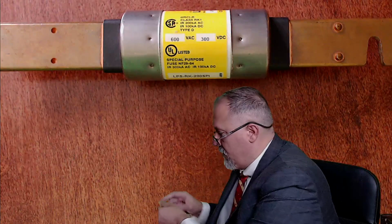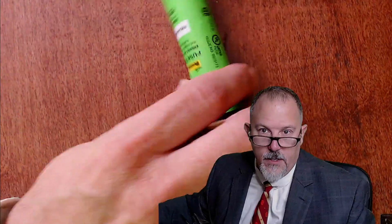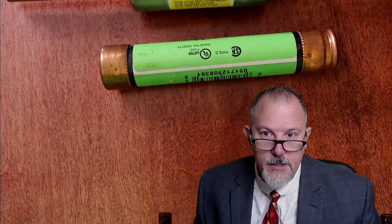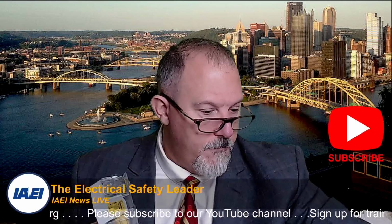Here's another fuse. This is sort of a typical fuse that you might see. Just a cylindrical tube, ferrules at either end. There's no possible way for you to connect a wire onto these devices. What this informational note reminds us of is the fact that we will probably need a block, a fuse block.